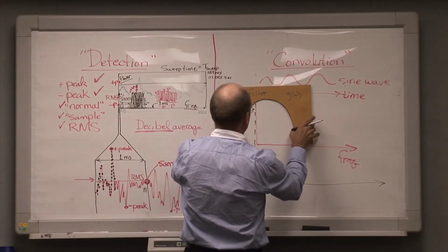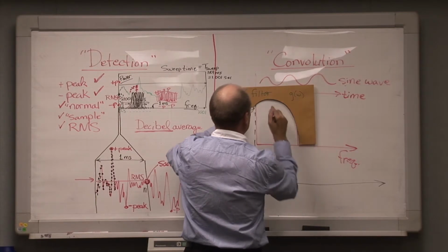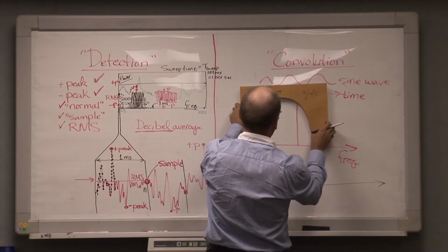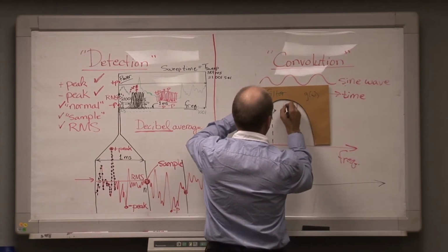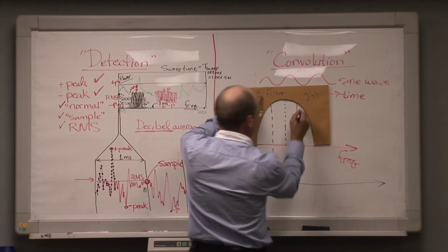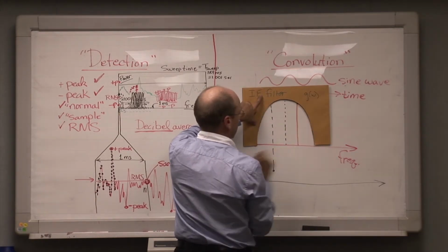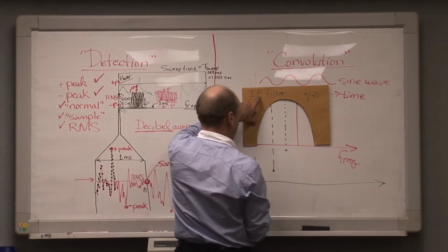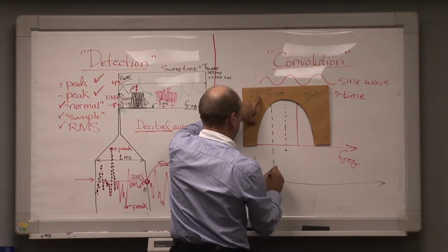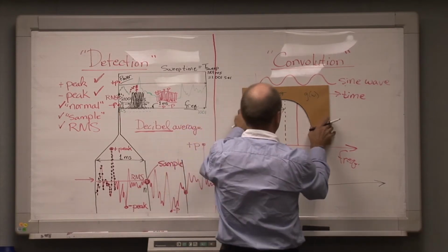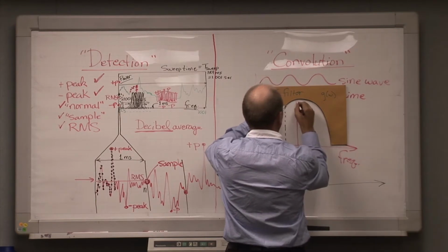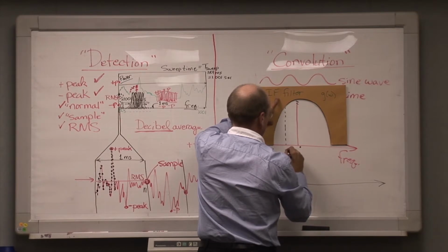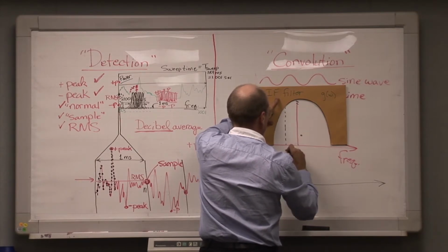Now we step the filter across like this. We'll measure noise again. Now we step the filter across like this. Now, at this point, although we're tuned to this frequency, we're getting this much power from this sine wave, and so now we see a power level displayed up here. So up to this point we were measuring noise. Now we begin to get power, step across like this. Now we get the full power in the waveform displayed on this frequency right here, like so.